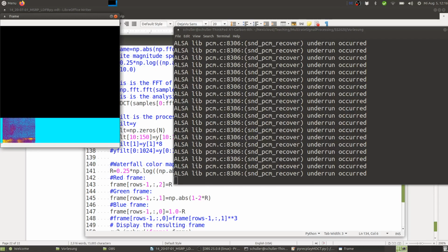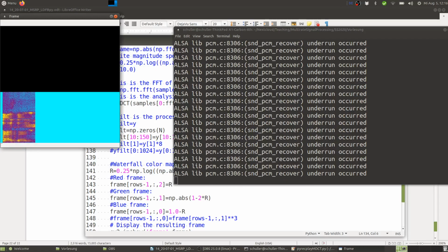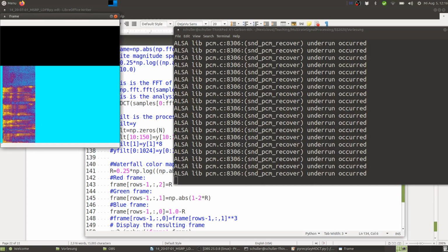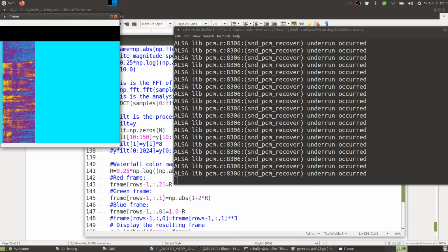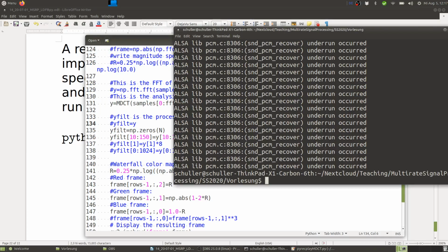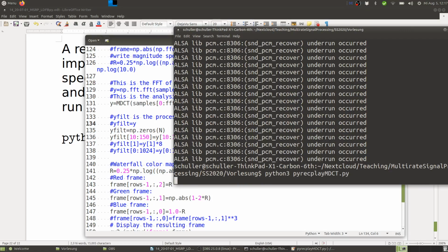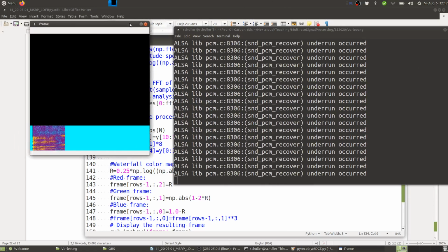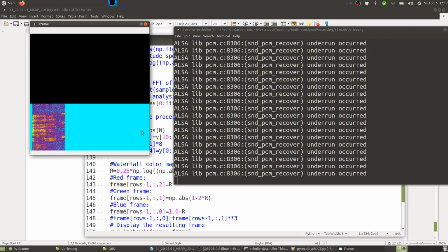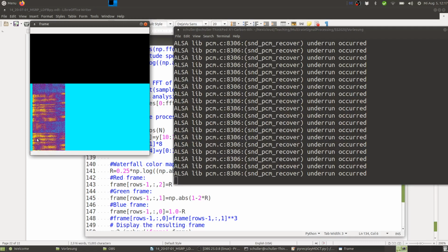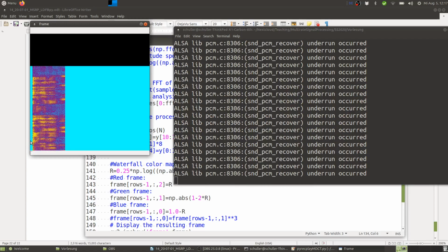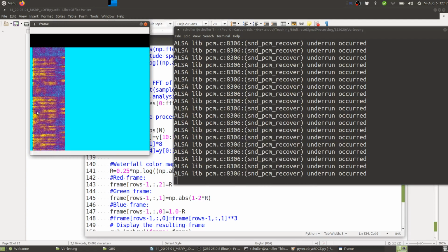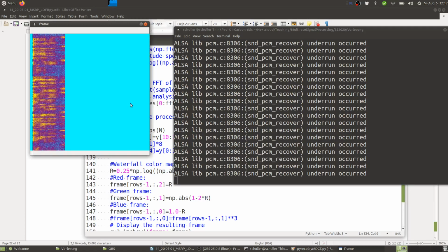So this is now my narrowband speech. 1, 2, 3. Yeah, so if you listen carefully, you can actually hear that all those high frequencies are missing. And you can also easily see it in the spectrogram. So here in the spectrogram, you can see the high frequencies are all blue, which means there is nothing there. It's all 0. And also the lowest frequencies here, they're all 0. And what's left is just this patch in the middle.